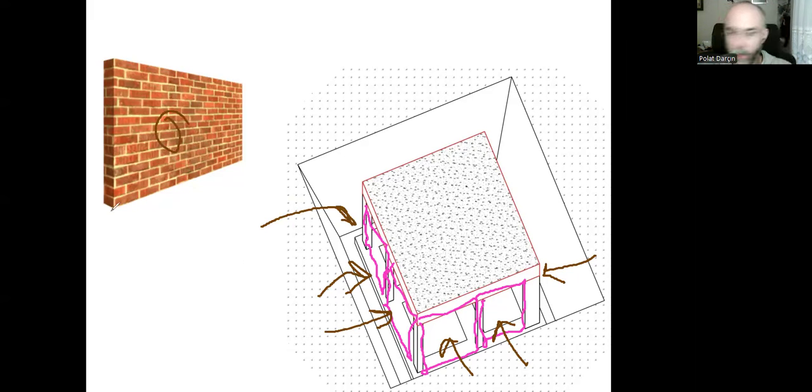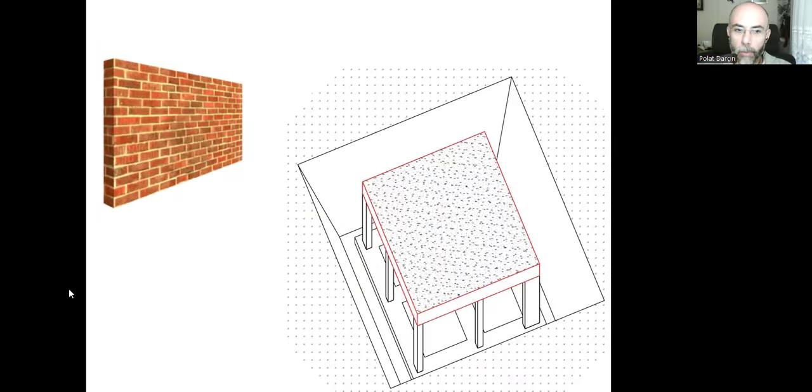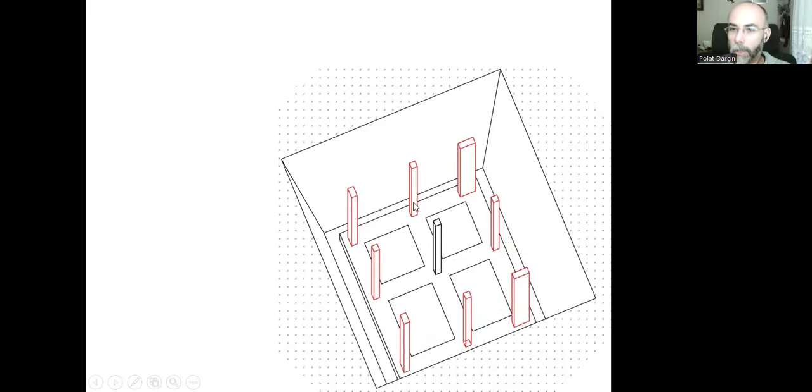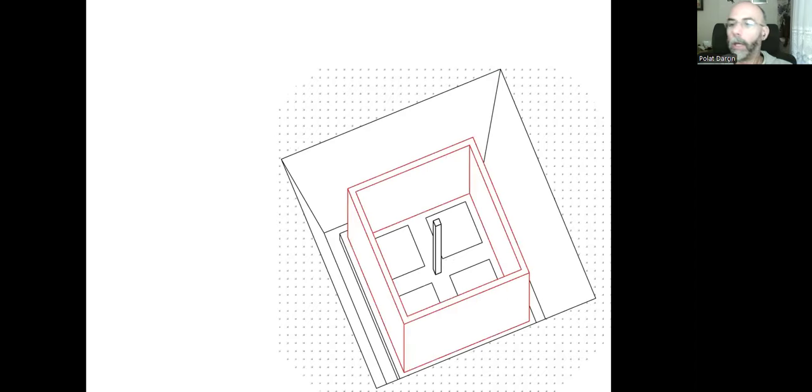They don't have the capacity to carry all that load. So it will be inappropriate. They will crash down. So we need something stronger. Instead of creating different columns in the outer surface of this basement floor and placing a reinforced concrete floor slab on top of it, we can create shear walls, not separate columns and beams, but a shear wall.